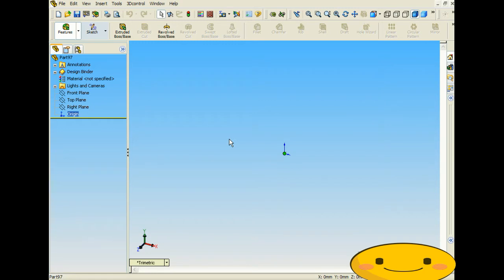We're going to do this because all of the major planes, the front plane, top plane, and right plane, run right through that point. Plus, it allows you to manipulate your part and create it the best way possible and implement it, say, in an assembly. It gives you more flexibility and freedom to do more things with your part, just so that you know where the center of gravity is and have it at that origin.